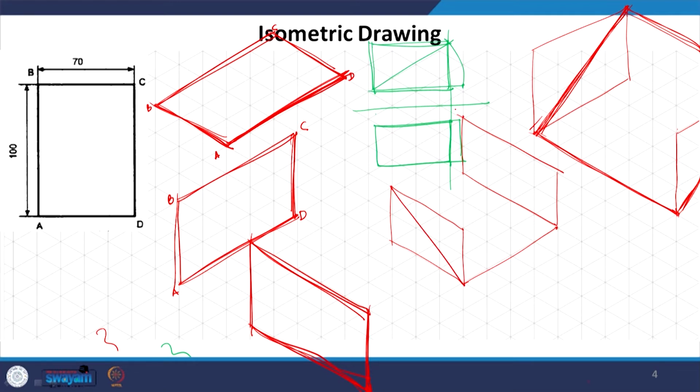So, now you can see that I made a mistake, and I immediately realized it because the line is not going to be parallel. The mistake that I committed was, here I measured say 3 units by 2 units. This is the reference rectangle, which is helping us arrive at the non-isometric line, the slant. And here I took 4 and 2, and the moment I draw it, I can immediately see that this is not parallel to this.